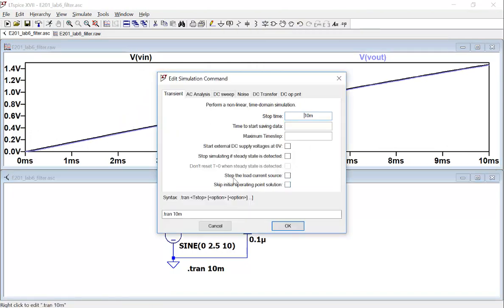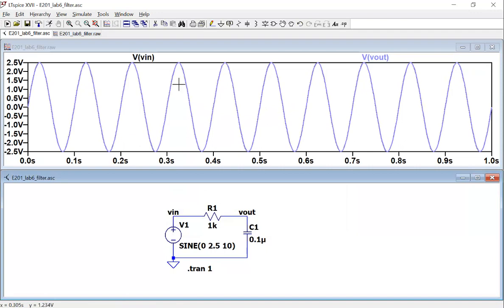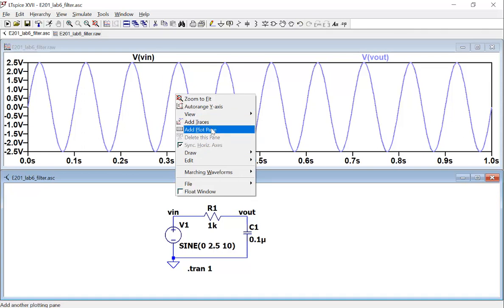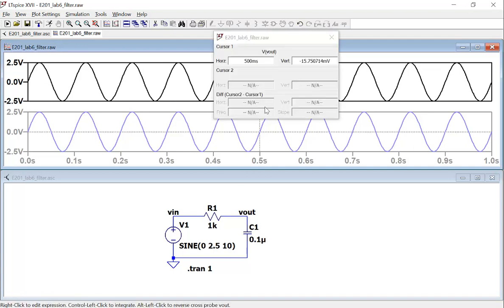I have to change the simulation time in LTSpice, but you are not doing LTSpice. And for 10 hertz, I'm going to run, for example, let's do 1 second. Should be adequate for that. Where's the output? They're overlapping, no? Why? Because the frequency is pretty low, so pretty much nothing is getting attenuated and shifted. But I still want to measure it to report the results.